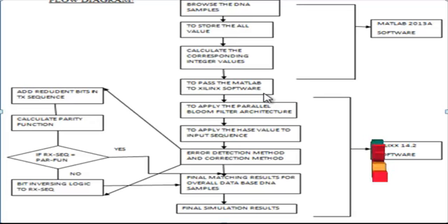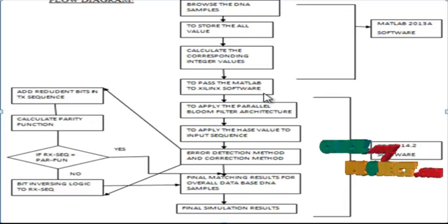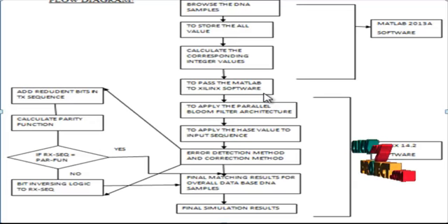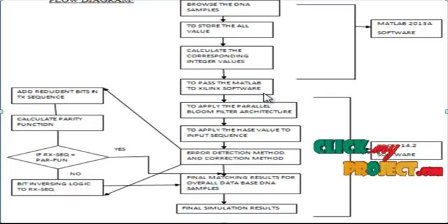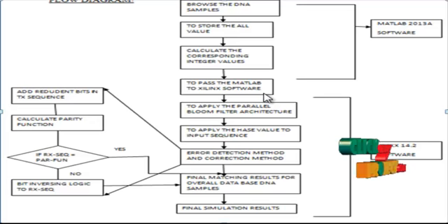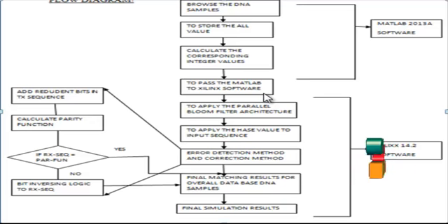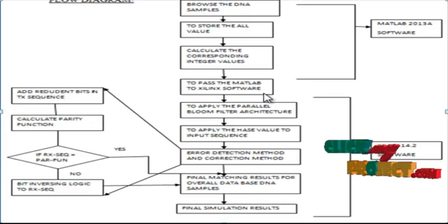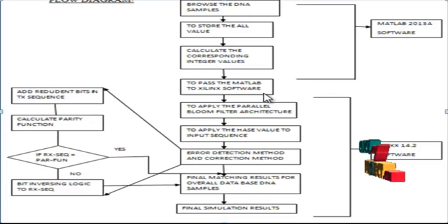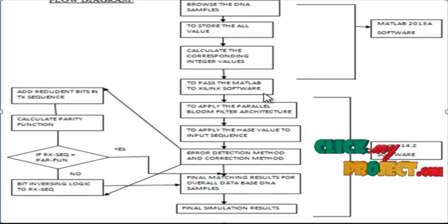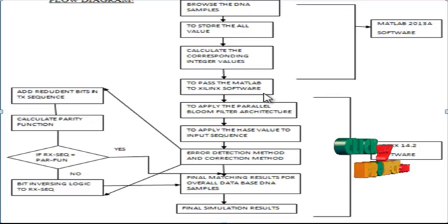Then we calculate the parity functions, replace the zeros with the parity bits, select all the data bits and transmit them. Then we apply the error bits to see how the error is corrected and detected in our required architecture. We pass the error bits to the transmitter section, then the receiving section reads all the values, identifies the parity bit calculation, and finally detects the error bit location.